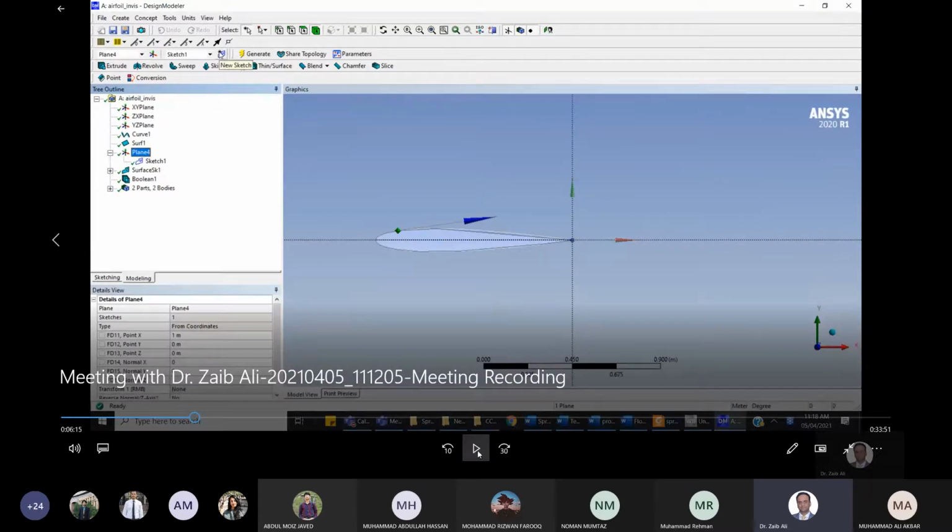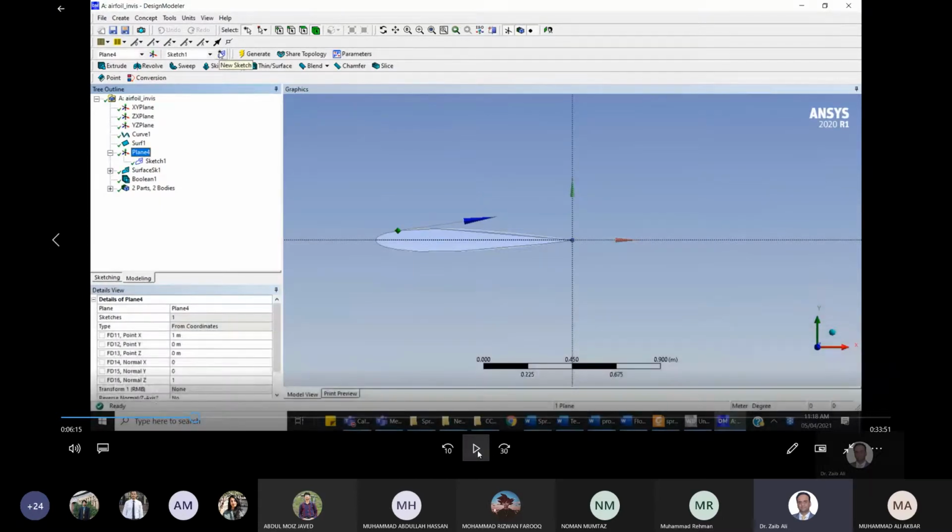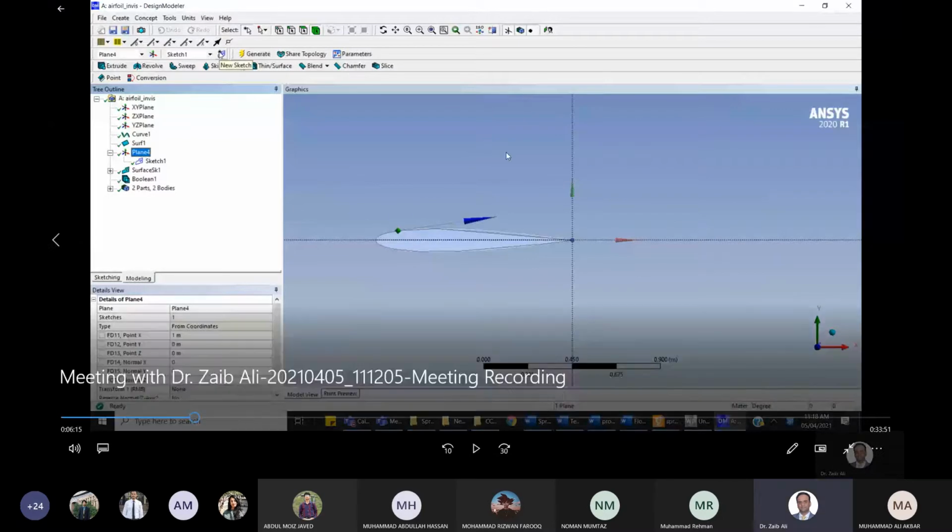of the aerofoil surface from the bigger surface, next thing you want to do is, for our subsequent meshing operation, you want to divide this domain into 4 parts or quadrants. So this will be helpful, as you will see later, for our meshing operations.